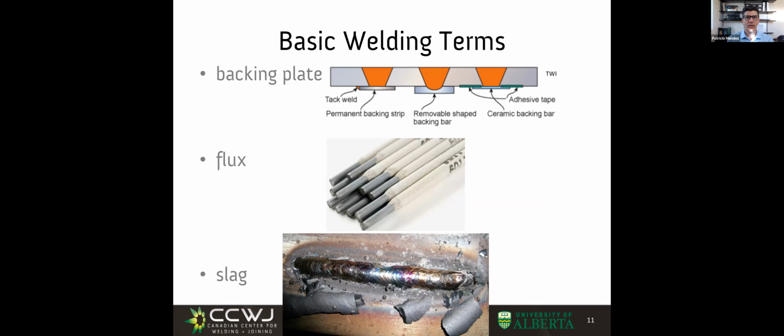For example, if you're welding steel, you can have a little steel plate that will prevent it from dripping through. Now, this steel plate might melt, and then you never get it out. That's what is called a permanent backing strip. I'm going back to the concept of fit for service. Pretty? No, it's not pretty. But if it doesn't matter, it doesn't matter. And you leave it there.